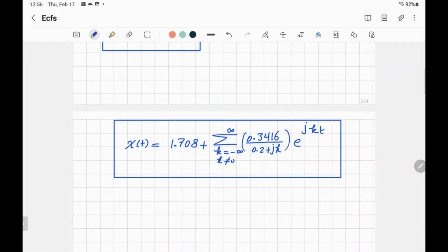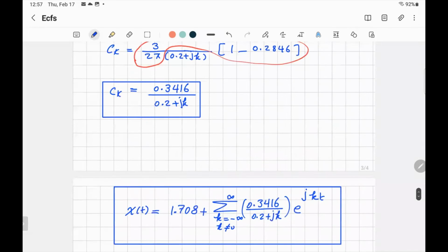As we said, the important information that you want to get from the Fourier series, whatever form you're using, is the magnitude spectrum and the phase spectrum. That's the most important thing. That's the objective. You want to know every single component in this signal, what its amplitude is and its phase shift. That's all. How do you get that? Using the Fourier series, even if it looks complex, you use ck. As we said, ck is going to tell you all the information: the amplitude, the phase, everything.